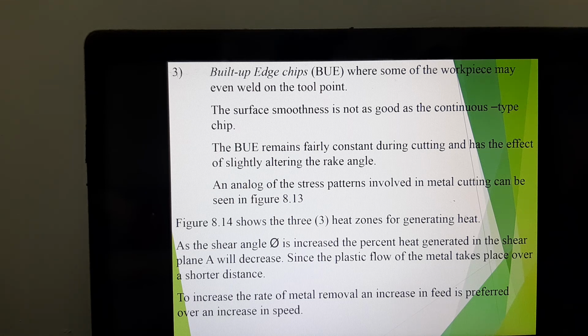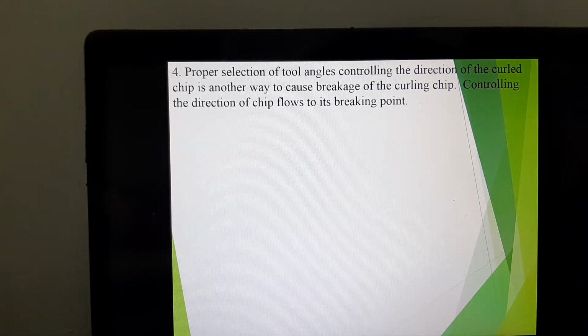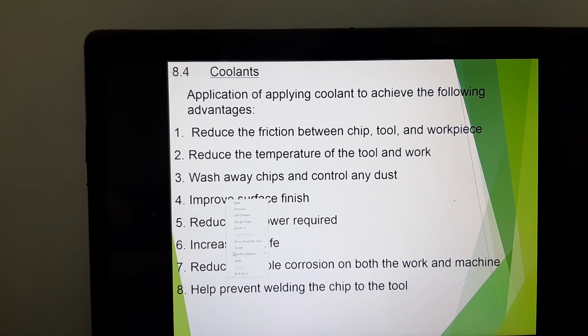And once it welds against your tool, the tool will become damaged. It's not like paper sticking to paper, yeah? It is metal sticking against metal, and it's going to be a permanent weld, and you cannot do anything about it. So in order to prevent that from happening, when you're dealing with an overly ductile material, you must make sure that your cutting tool has a chip breaker.